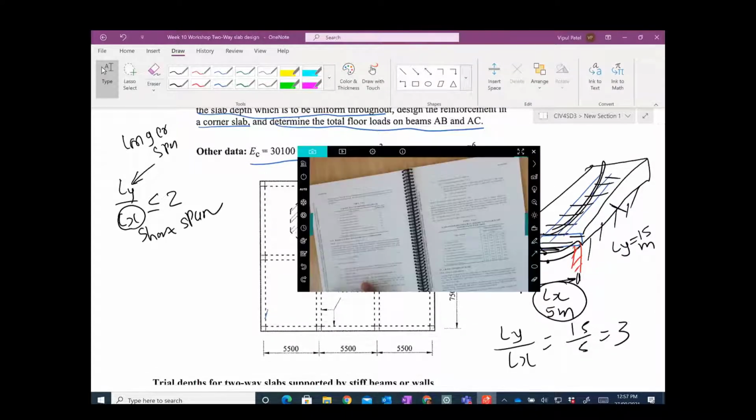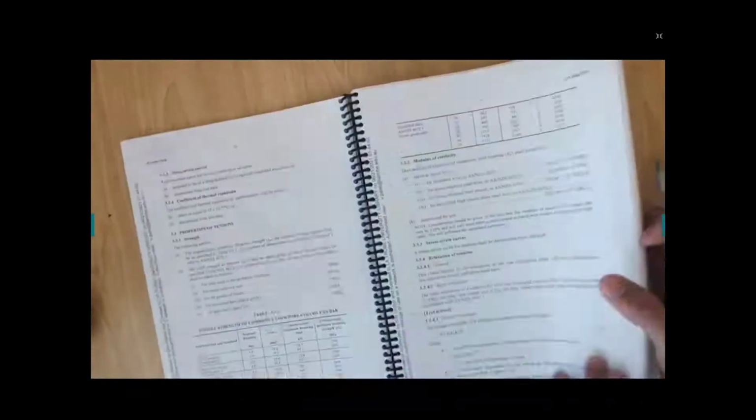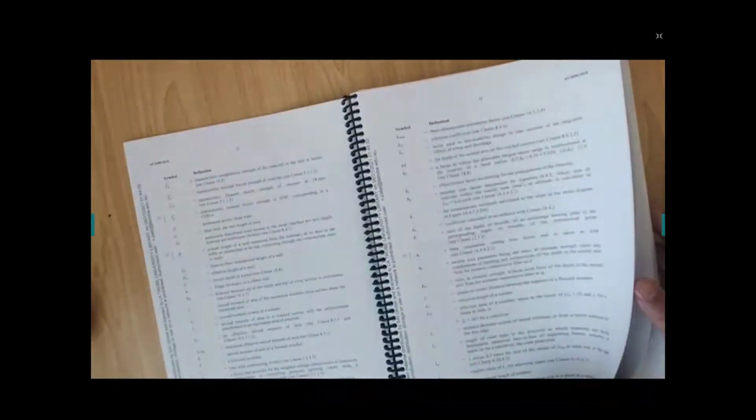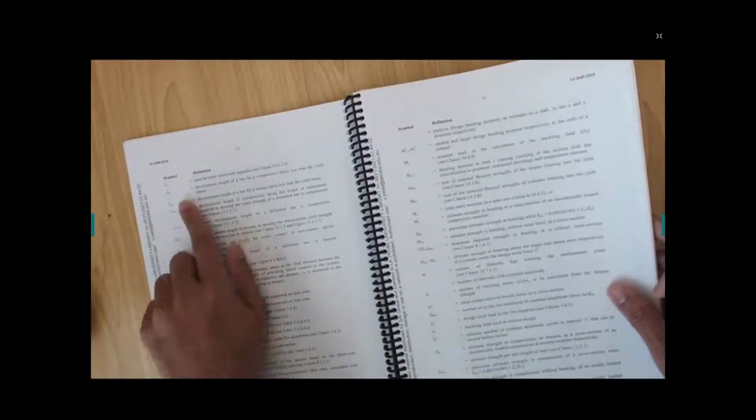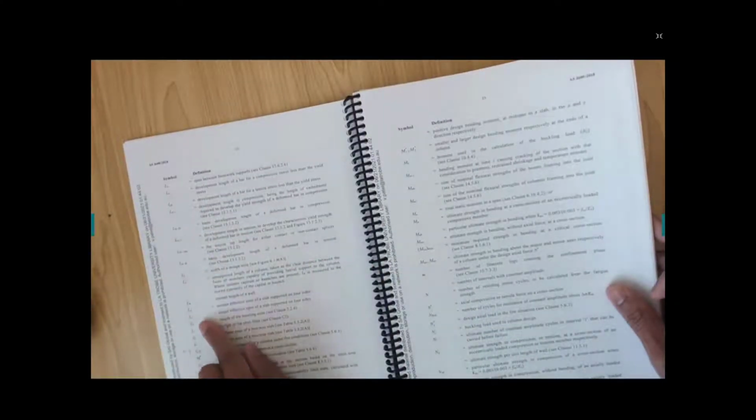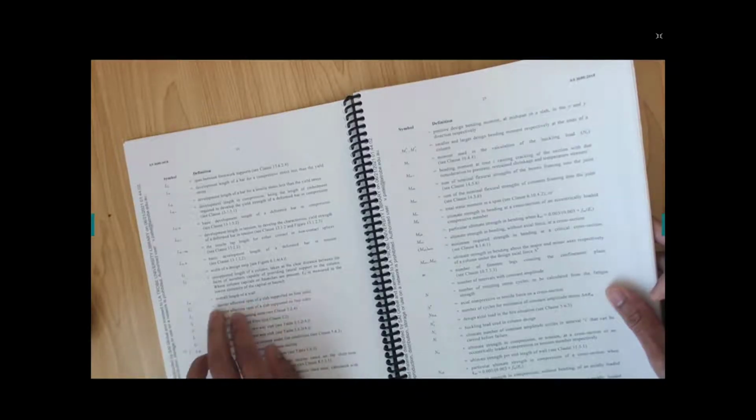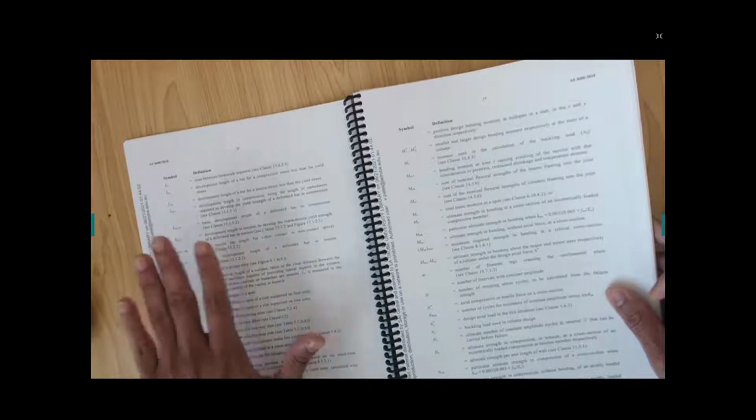So in that case, you go to the standards at the front, and somewhere they will write about that, in alphabetical order, as you know, length, Lx and Ly. Lx is the shortest effective span of the slab supported by four edges. Very useful information: your Lx would be the shorter effective span and Ly is the longer effective span.